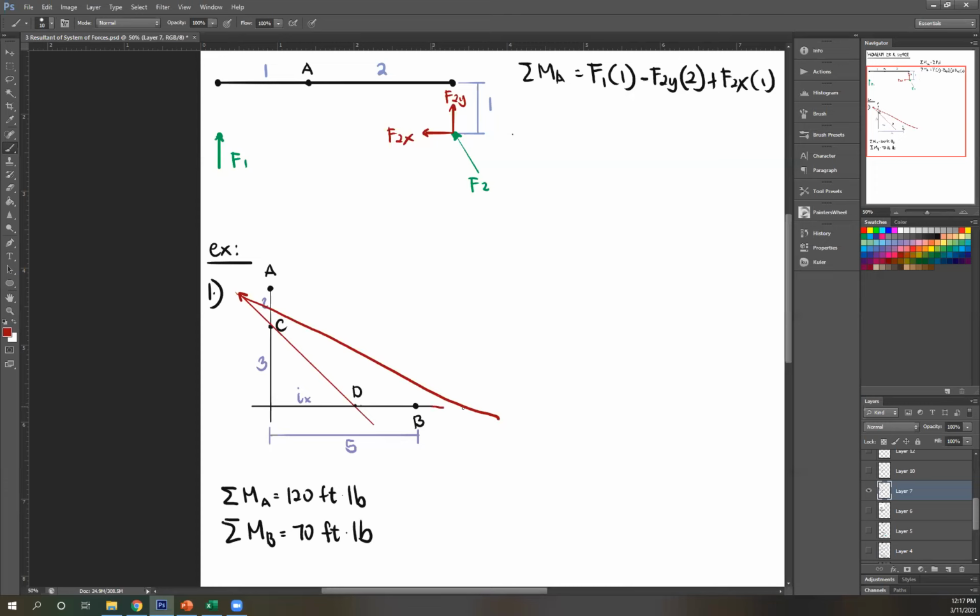So let's check. If my force is outside of B, the direction is this way, right? Rotate this about point B. Rotating about point B, you get counterclockwise. So no, your force will not be outside of B. Therefore, it's inside of B. This is the correct drawing. Okay? So to check, once again, try to rotate this about point B. Once again, your direction is this way. So rotate, and you get a clockwise direction. So positive. Correct. So now that's your drawing.